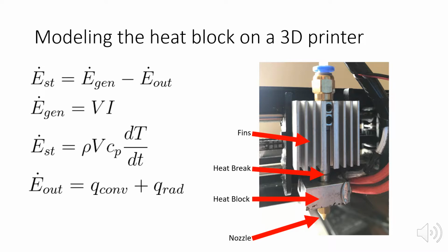On this model, there is no fan cooling the fins or heat break, so there is only free convection. Free convection on opposing sides are the same and will use the same H value. Combined with free convection on the top and bottom surfaces, there are 4 H values that will need to be found during each iteration. HR will also need to be found. The emissivity is assumed to be 0.5.